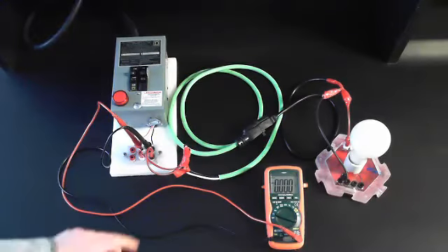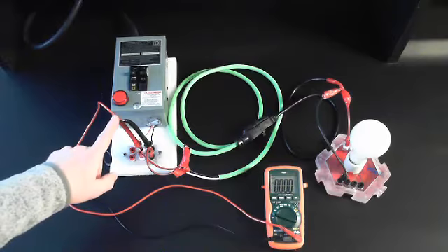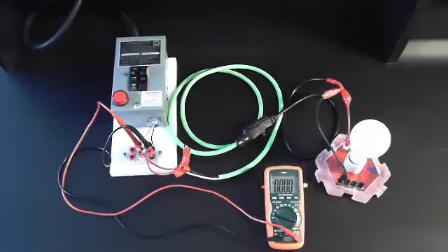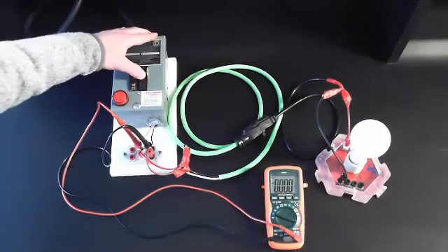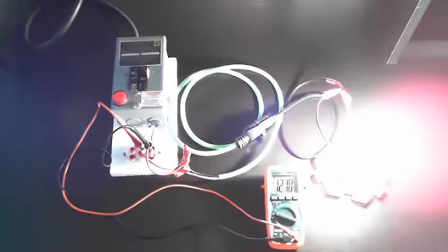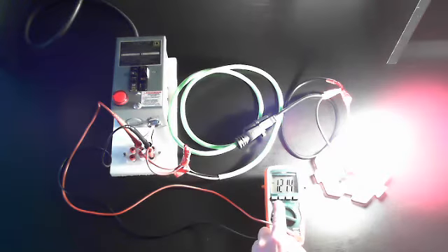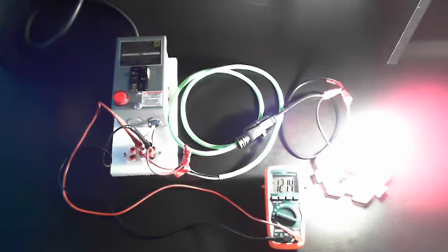We're going to have measurements of the box, the source voltage, and then the load voltage at the light. And we'll see the differences. Then we're going to add different numbers and lengths of extension cords. Of course, after that blinding light subsides slightly, we have a total source voltage of 121.5.